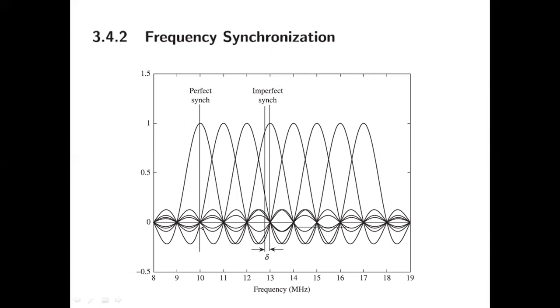That means if you want to receive, you better have your subcarrier frequency tuned at this particular FC only. If you go a little here and there, although you have your original frequency data at that point, you can see here is the culprit. You have the contribution from the neighboring subcarrier, this one here or this one here, non-zero. Now that's a concern.